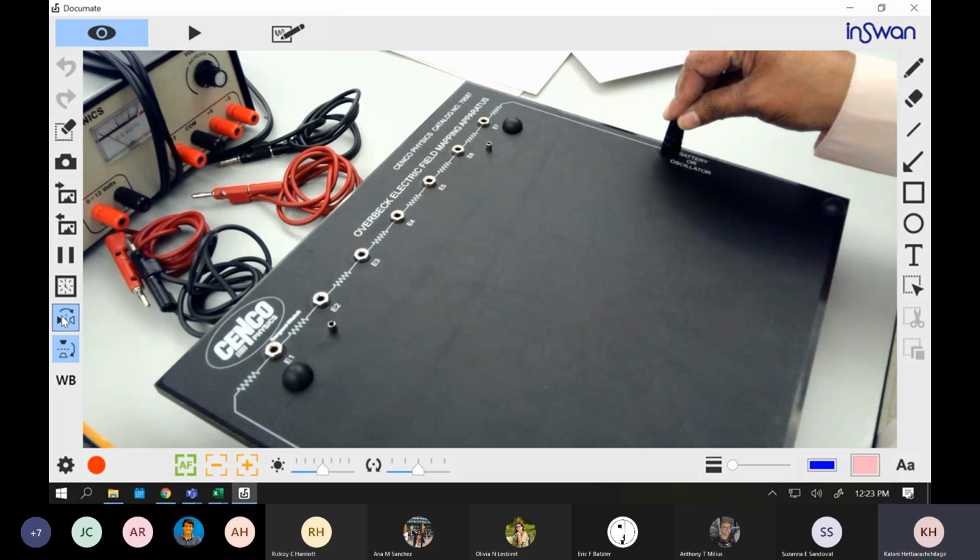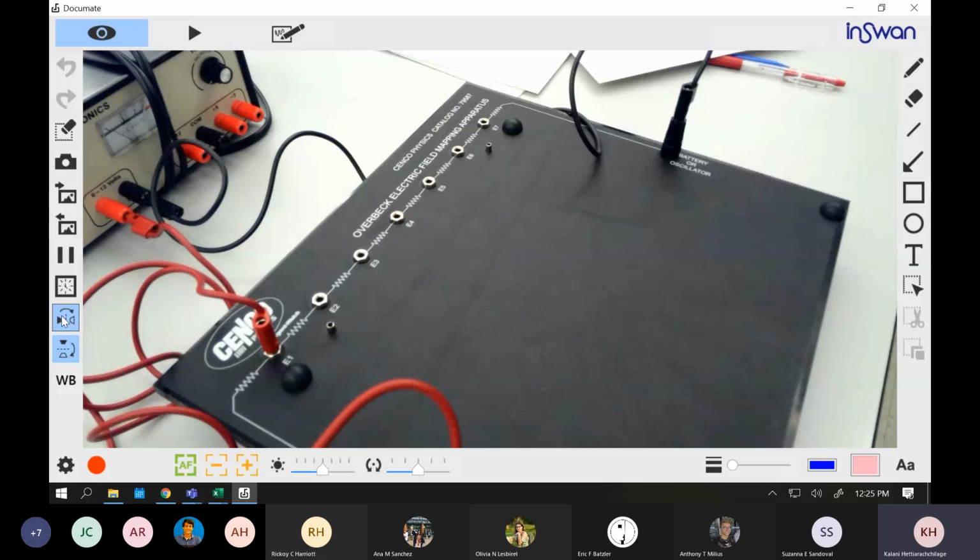So I'm going to leave this on the other side because I'm not able to use that in there. And then take the black one, and you're going to connect that to the COM of your voltmeter, right? The COM is next to your red one. So connect into the COM, and then you're going to connect this black into the probe. So this is the probe, and you're going to connect into this hole in here. Okay. So now our circuit is connected.